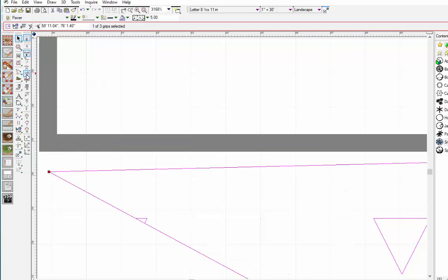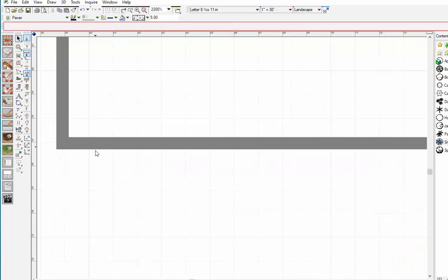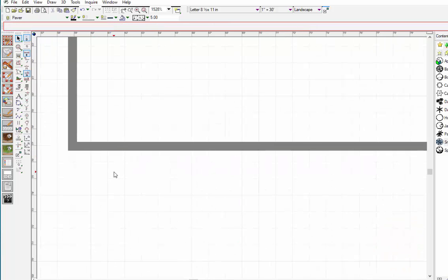Okay, if I have the nearest point snap on, which is the letter N on the keyboard, and I pull it up, you'll see that it wants to adhere to the center line of that foundation wall. So when I would go in here and fill in with grass, it's not going to leak through this area here. Okay, so it's important whenever we're drawing in pavers to use snap tools to help us through this process.